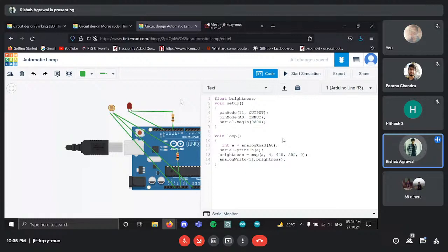That should probably be the maximum value the LDR would read. But the safest way is to simulate the same environment your robot would be in, and read the LDR values beforehand for all possible conditions. Okay, thank you.